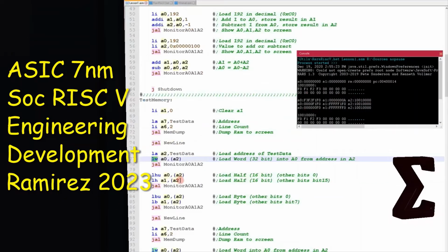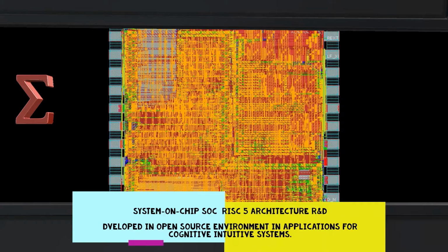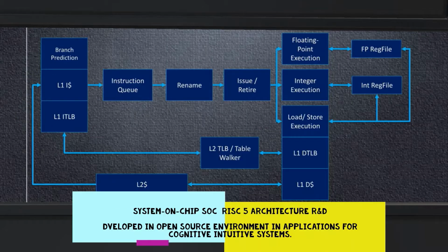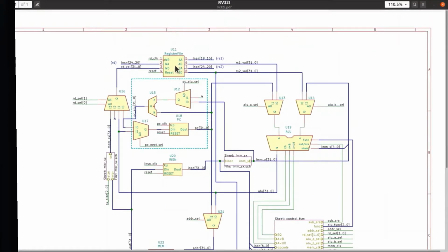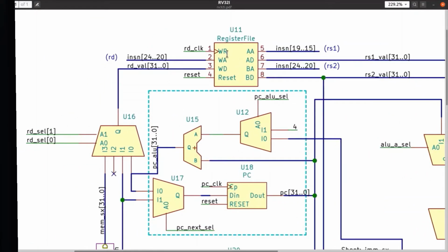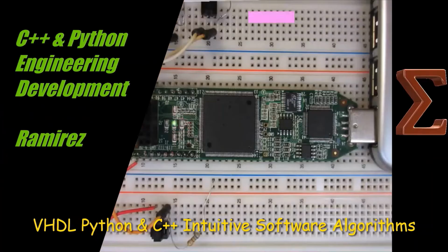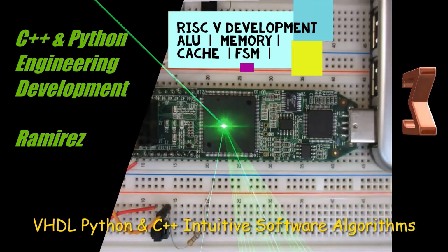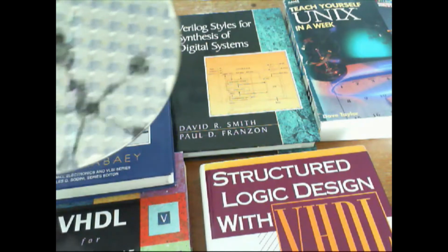For those sections of the design that are full custom, we have the choice between manual porting and automated porting. Under certain circumstances, automatic porting tools such as Gigantic Dream can be effective. These tools operate at the polygon level, automatically mapping transistors and interconnect from one set of design rules to another, and shrinking the design as much as possible.